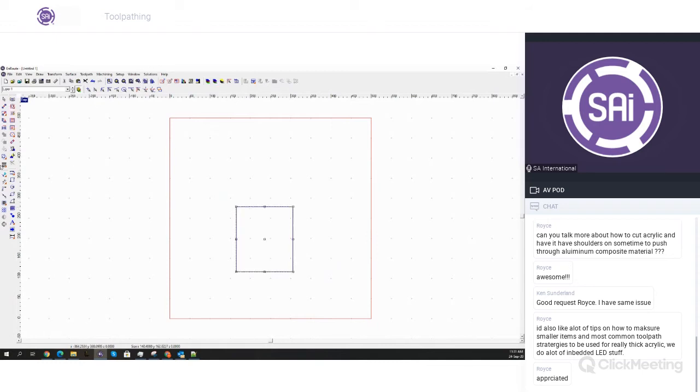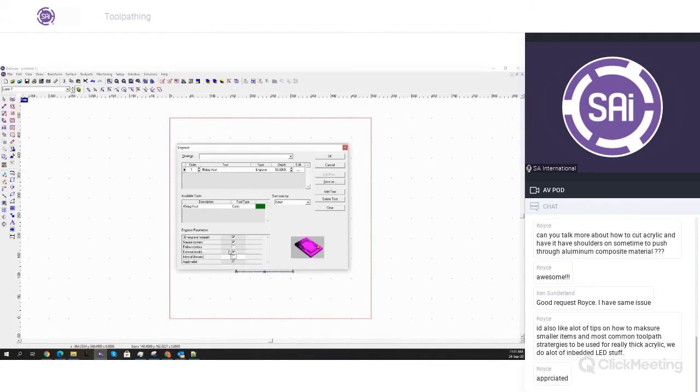If you have a curved line, or a waving line like we saw last time when I did the rapid texture, you have the possibility to follow the contour. So if you import a DXF which has a bunch of contours that vary, for example, in the Z-axis, following the contour will simply require you to set the depth here.